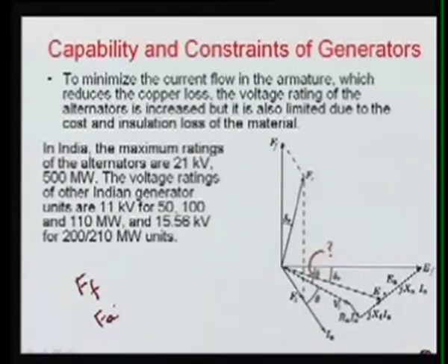If you see here, we have the armature currents, and the resultant of this armature, because we have three phase windings displaced by 120 degrees in space, Ft, will also be rotating in the air gap. This flux, that is MMF, will be rotating at the speed of the operating frequency, omega equals 2 pi f. So the field MMF Ff is rotating at synchronous speed, and Ft, due to Fa, is also rotating at the same speed.